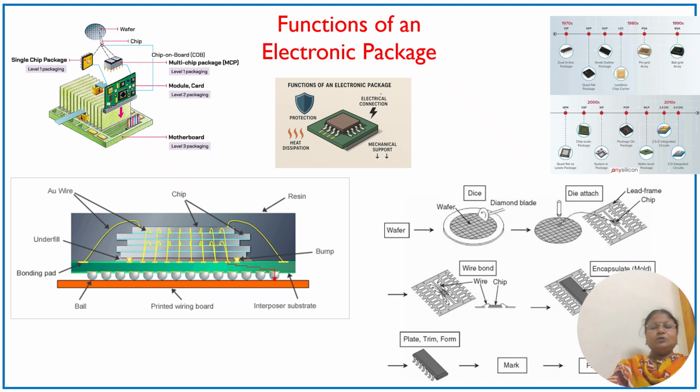Either it is made of aluminium, or you can go for a high density one, or with a high cost, gold wires are also used, with very high precision in the case of a sensor unit. This particular wire is taken for signal connectivity, and from this bonding pad on the substrate material, it is connected to the chip, which is placed on top.